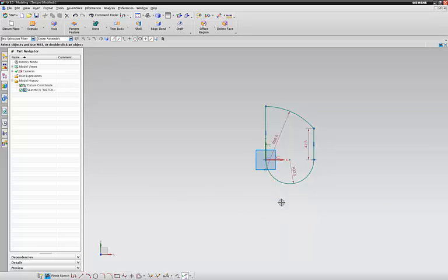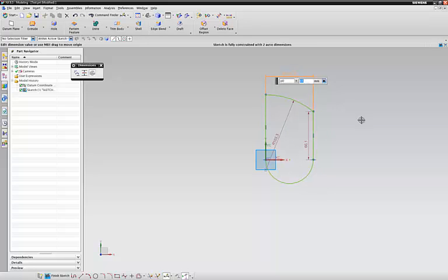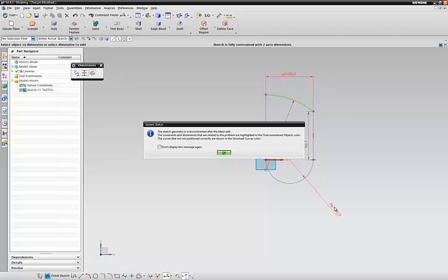One important thing to know about the dimensions is the software will automatically define everything for you, but if it's in yellow or if it's in red, it means the dimensions can be changed and are not specified by us as a certain dimension. If we want the dimensions to be solid, we click on this one right here. It'll create a blue line and dimension it, and we can add the dimensions that we want to our part, or to the lines, or the arcs.